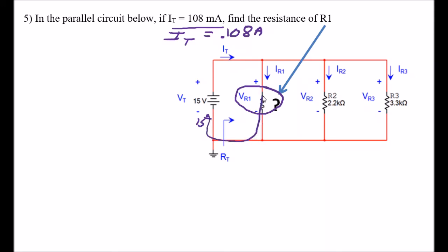So if he goes this way, he's lost all 15 volts through that resistor. If he goes that way, he's lost all 15 volts through that resistor. 15 volt drop across any of these resistors. So I'm going to use that first to calculate the current in each of these little branches right here, just using Ohm's law. V equals IR. What could be better than Ohm's law?